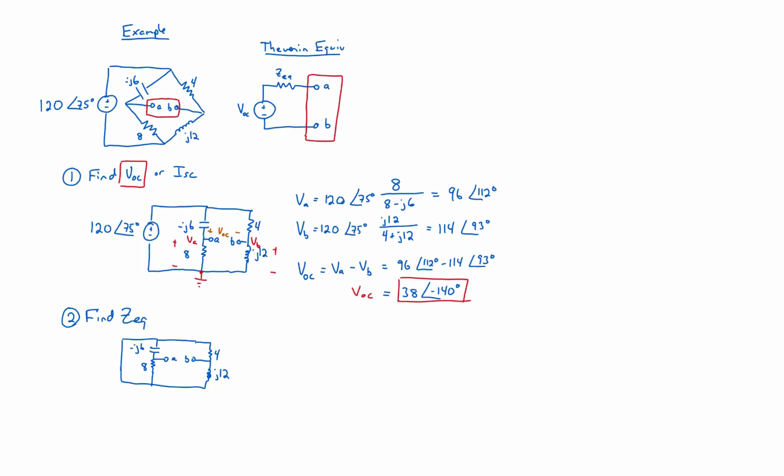And you might think, well, this capacitor on the left and the resistor on the left, they look like they're in series because all the current that goes to the top would have to go through the bottom. But that's true if the current was being injected from the top, but it's not. We're looking for the impedance between points A and B. So we're pushing current into A and we're extracting it out of B. And when we're pushing it into A, actually the current splits between these two. So they're definitely not in series.